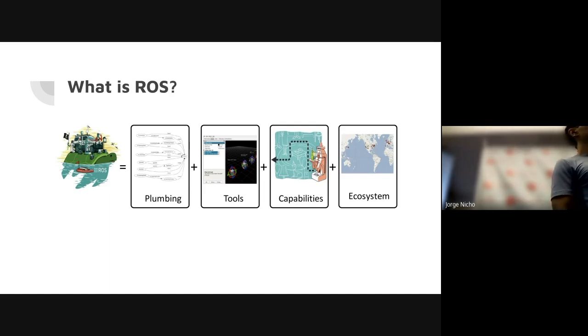So there's some hardware standard you have to meet, and as long as you meet that, you can use ROS with it. The standard is the message interfaces. If you're a robot vendor and you want to support ROS, you write your software and then provide an interface presented as a message for, let's say, accepting joint values. As long as that is provided, the software somebody else wrote to control your robot will have to send a message in that particular format. So they both can talk the same language. That's really the only requirement.